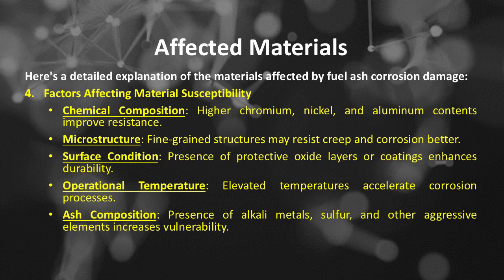Surface condition: the presence of protective oxide layers or coatings enhances durability. Operational temperature: elevated temperatures accelerate corrosion processes. Ash composition: the presence of alkali metals, sulfur, and other aggressive elements increases vulnerability.